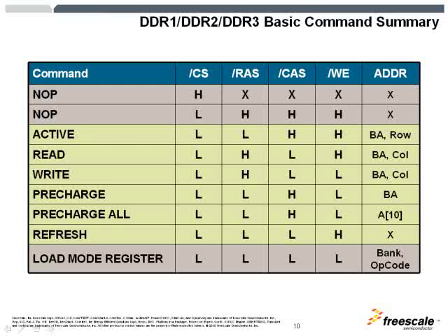The pre-charge, or closing of the row buffer, again needs to access the row to put that information back in there. So we have the row access command activated low here. And you also have pre-charge all and refresh commands here for your reference.